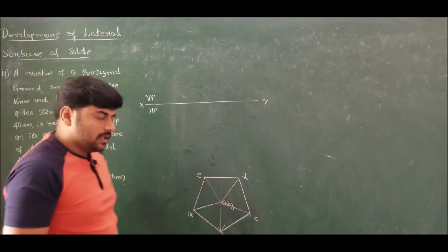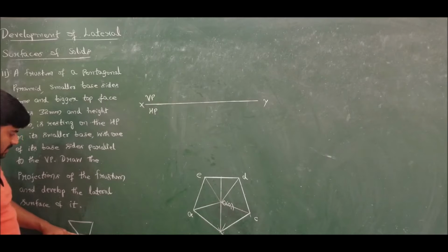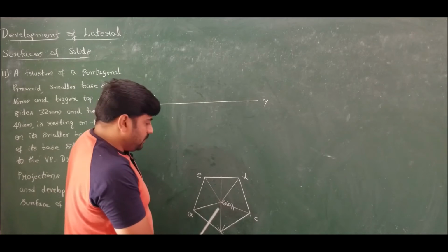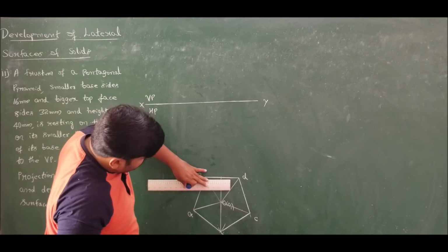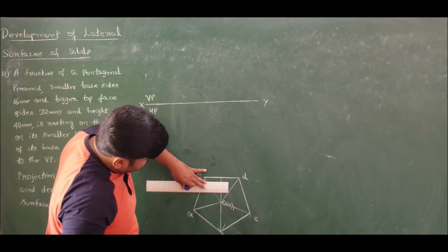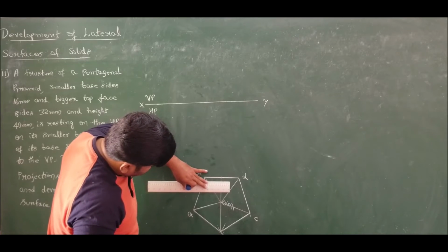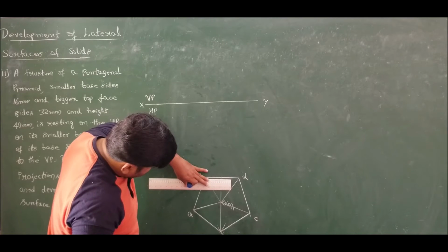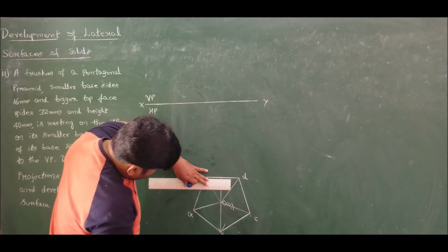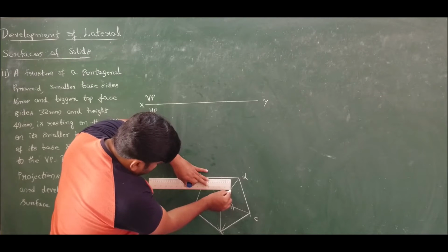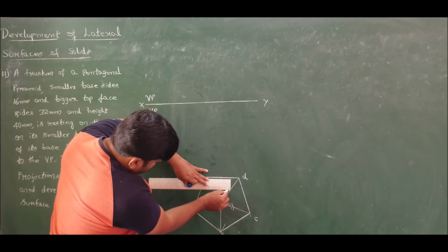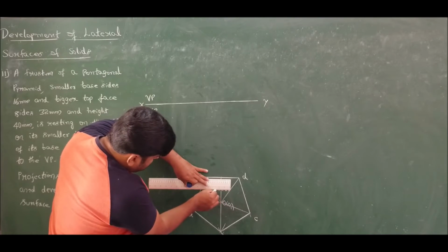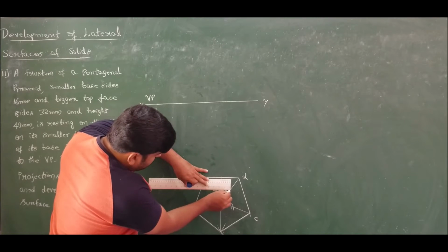Done. Now the bottom face of this is 16 mm side. So I should draw one more pentagon, the bottom face of 16 mm side. For which first I will mark 16 mm by taking 8 on either side. Identify 16 mm on this one. So I identified 16 mm on this one. Since it is converging like a hopper-like structure, the inner face is invisible.